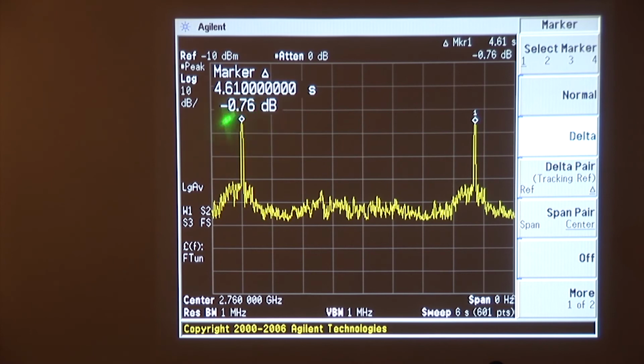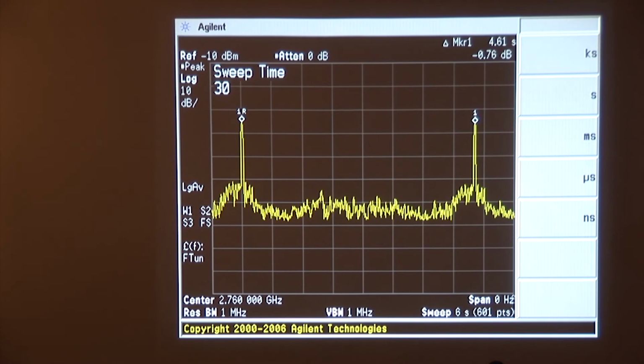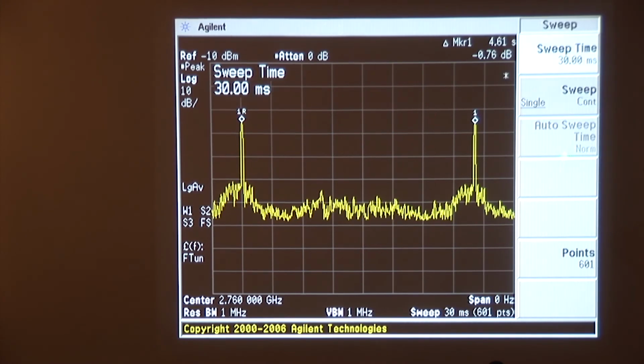Next, we're going to look at what's happening right here, right inside the main beam of the radar in time. Now, air traffic control radars typically put out about 1,000 pulses per second. We know that they typically put about 20 pulses in the beam because that's where they get their optimum signal-to-noise ratio. So if we want to see what's going on inside the radiation pattern of this antenna right close to the point where it's looking at us, we want to go for a little more than a 20 millisecond interval. Let's look at about a 30 millisecond interval. And we want to trigger a sweep just as the radar is looking at us.